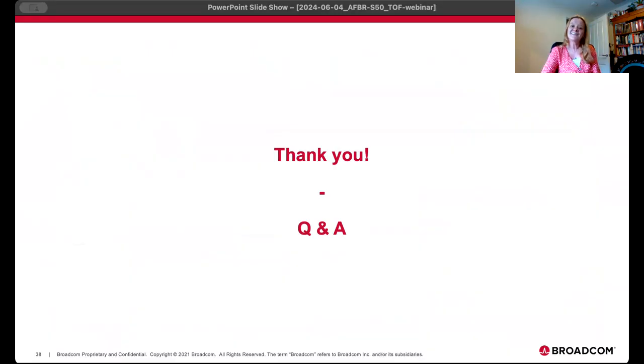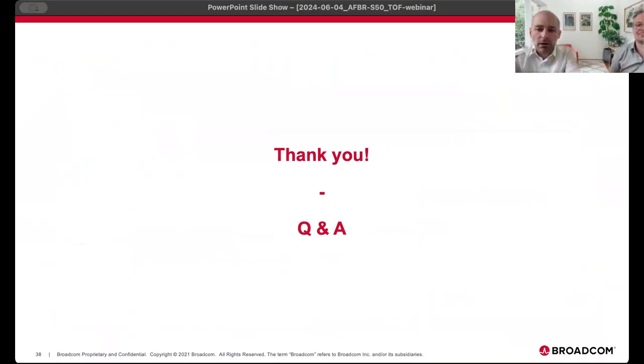Yeah, so actually we're working, as mentioned in the beginning, with a 32 pixel array. We have 4 × 8 APD pixels. This is the resolution for each sensor. And we have for all our variants a pixel field of view of 1.55 degrees times 1.55 degrees. So this is the resolution you can achieve. But I would also like to add that our sensitivity is so good that if the object is smaller than this field of view, in most cases you're still able to detect the distance to the object.